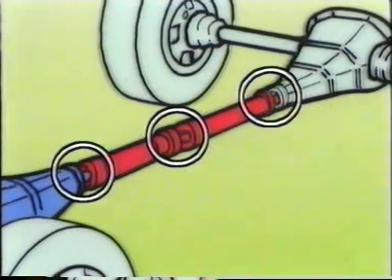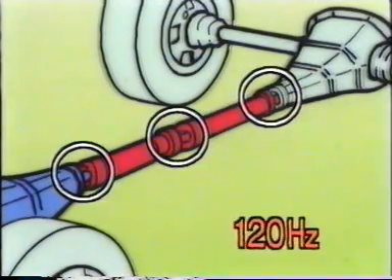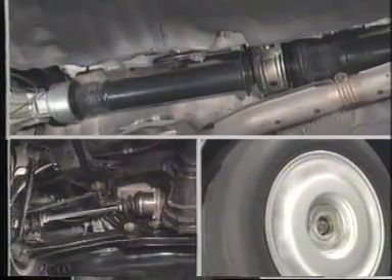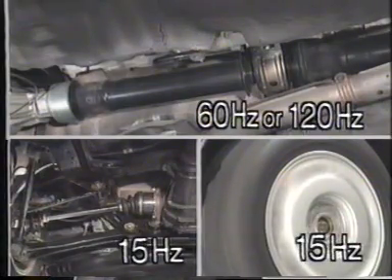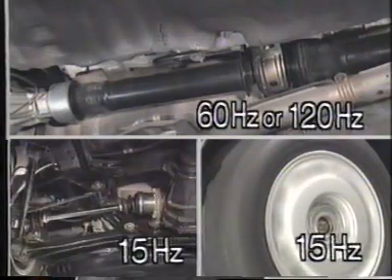This will cause vibration at a frequency of 120 Hertz, or twice that of the propeller shaft. As you will realize by now, you can identify the vibrating force if you know the frequency of the vibration about which the customer is complaining.